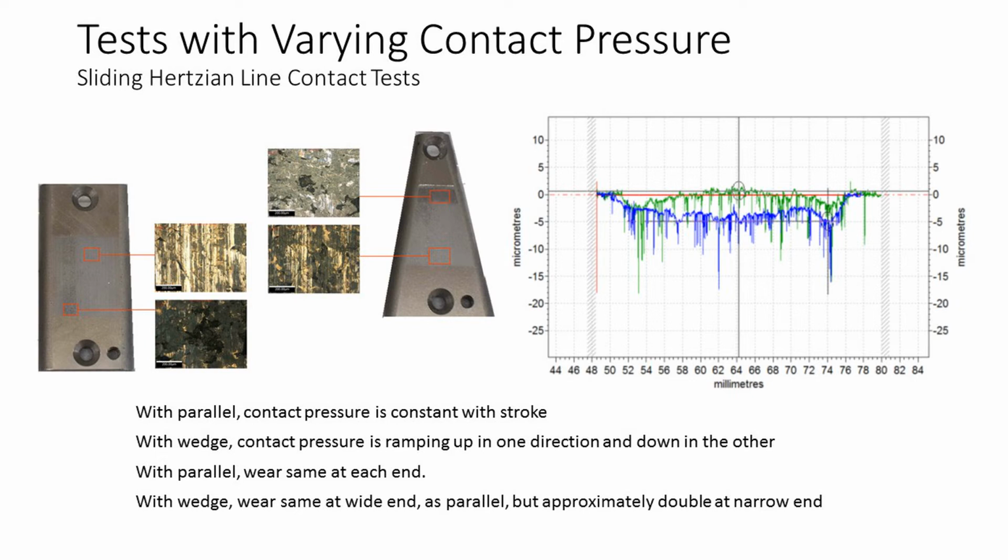Repeatability with curved edge plate specimens and overlapping pin samples appears to be good, compared with tests where the contact width is less than the plate width. This suggests that in the latter case, variable edge effects may have an important influence on repeatability. Provided that the wear mechanism is the same at either end of a wedge specimen, the friction is independent of nominal contact area. Time-smooth friction provides little information with regard to wear transitions under mild regimes.